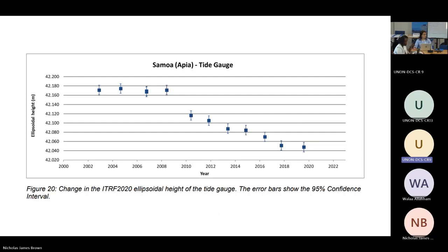Thank you. That's exactly as I understood it. This is something for us as land lovers we struggle with, and it's taken me a long time to understand this. Offshore, they're using mean sea level as a reference point, and then with that they also have the mean dynamic topography to deal with. So you can be above or below mean sea level depending on the time of day.